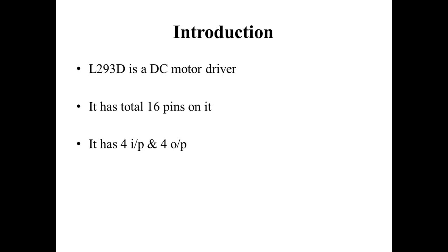So this particular L293D will be intermediate between the microcontroller 8051 and the DC motor, which we are using of a 12 volt type. I'll have a 12 volt DC motor, which I'll be controlling with the help of this microcontroller using the L293D IC.